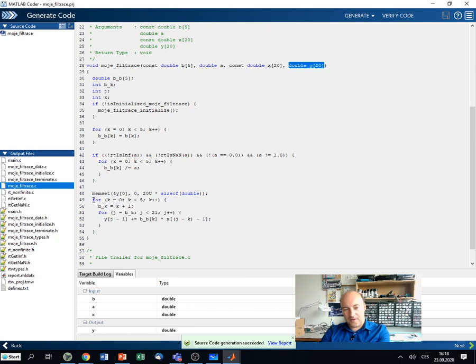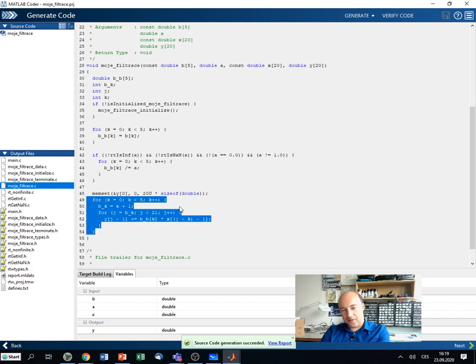The main filter algorithm is this. We can see that it's a for loop, and actually the filtering algorithm is only this line. Here, this is some coefficient times the sample, and this for cycle is the history. Because in my filter I have used 5 elements in the history, for this reason it is running up to 5. So this is the filter itself.